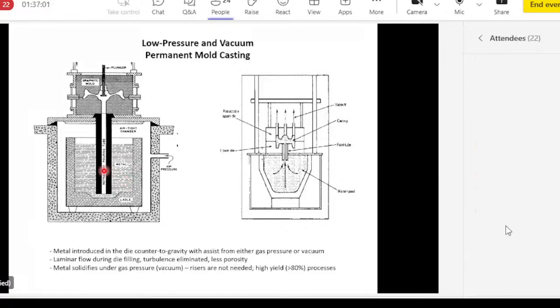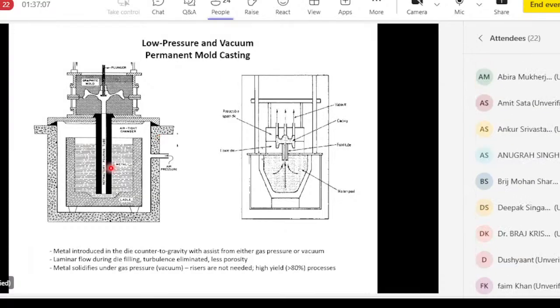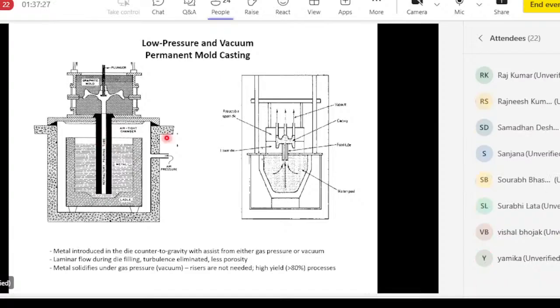Yeah, I remember many years ago in the early 90s, maybe about 40 years ago or so at NASA, I was using this process to make some composites. So what we were doing was slightly different. I'm telling this because I learned a lesson based on something that went wrong. What happened was we were trying to make some composites. So in this tube, we had some sapphire fibers. We could put this fiber like this in contact with the molten nickel. And then I would pressurize the chamber and allow the metal to rise through the fiber bundle under pressure.